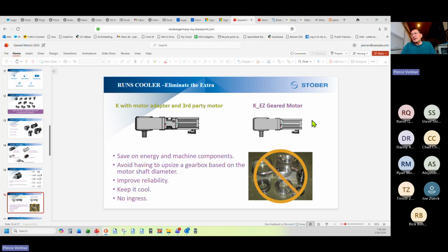If the manufacturer makes the motor and a gearbox as a unit, you can then eliminate a lot of this componentry, and the shaft of this motor becomes the mounting point for the first stage of the gear. This is very advantageous in terms of axial length.